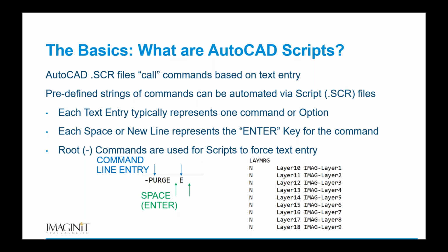So what that means is it's essentially just going to be typing in the letters at the command line for you. But instead of having to type them in manually over and over by yourself, you can predefine these in a text file and then just drag and drop them into AutoCAD, and it will run everything that you've got written inside of that text file. In order to set this up, though, it does need to be formatted in a quite specific way.